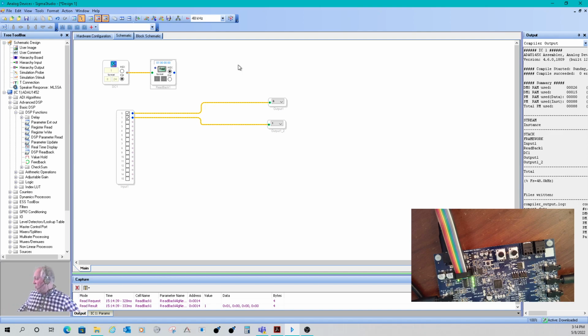Then you can go further. And of course, now I know this is going to work, but we can say, well, what if it still doesn't work? Well, now we're looking at the serial data, the audio data path. We've confirmed that the communication's good with the DSP, at least seems to be good.